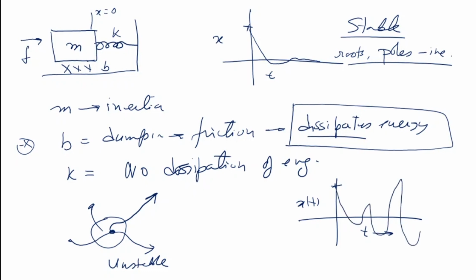This oscillation, instead of coming down, is going to increase. Okay, this is again an unstable system. So it is not coming back to where it started, it's going off somewhere else now. Okay, so this is an example of an unstable system now. So Alexander Lyapunov was the first person who observed that if you look at energy, then basically that is what can give you an idea about stability of a system.